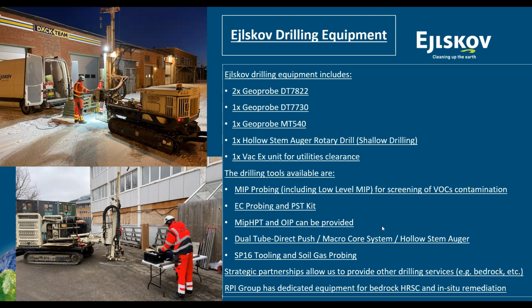We support the drilling machines with direct sensing tooling like the MIP probing. We have also low-level MIP if we want to go and screen some low contamination plumes. We have EC probes and PST kits for assessing soil conditions and hydraulic conductivity conditions at sites in a fairly quick and reliable way.